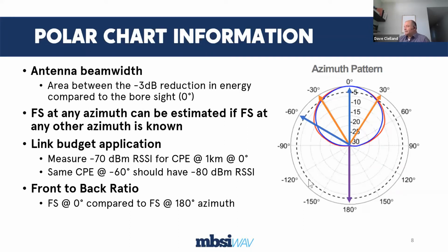So I will be minus 90, 90, 90, all the way around. The minus 150 will be minus 90. And when I reach the 90 degree point away from that antenna, my signal will start to rise. And at that point, I might be minus 25, and so then I'll be minus 85 and so on and so forth as I get back to the design azimuth of the antenna again.